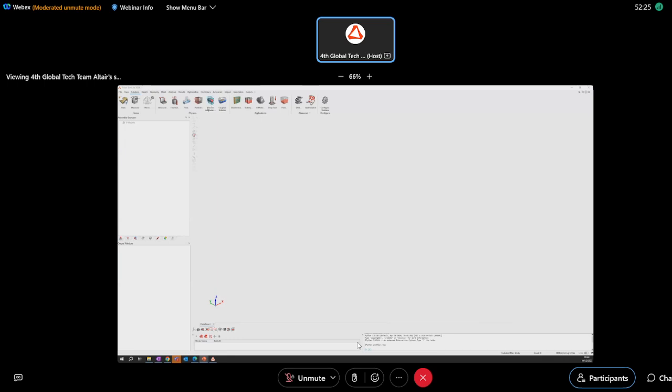Okay, so to create an electromagnetic solution, we can go to solution, electromagnetic, magnetostatic, and then a new window will appear. As you can see, we are going to set an axisymmetric magnetostatic case with domain axisymmetric. So we can click on OK. The name is not important, magnetostatic can be fine. The flux is set by default.